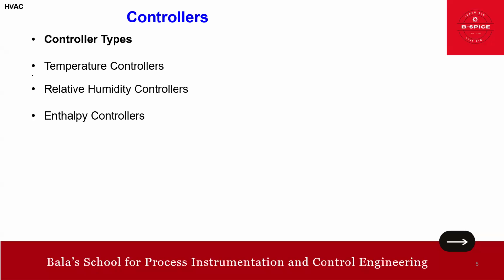Enthalpy controllers are specialized devices that use specific sensors for inputs. In some cases, the sensor may combine temperature and humidity measurement and convert them into a single voltage to represent enthalpy of the sensed air. In other cases, individual dry bulb temperature sensor or a separate wet bulb or relative humidity sensor provide inputs and the controller calculates the enthalpy.